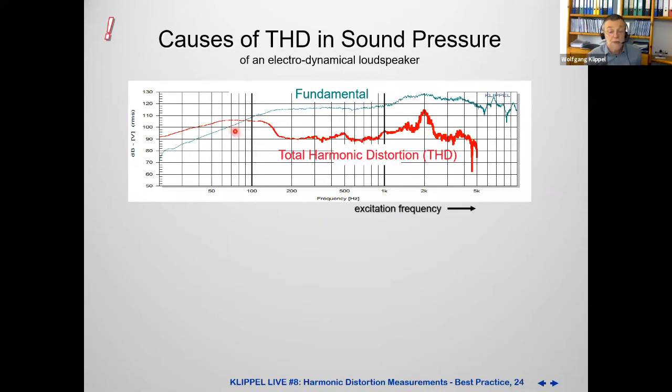Please keep in mind, this is the excitation frequency. That corresponds with the frequency of your generator. It's not the frequency of the second, third, fourth, fifth harmonics. They are at much higher frequencies. That's a little bit confusing. So that's our resonance frequency.